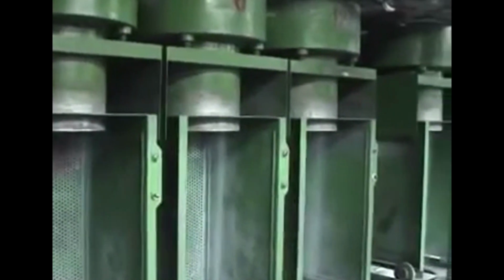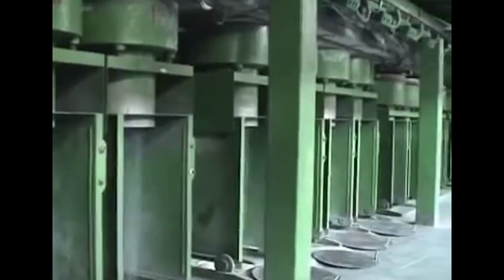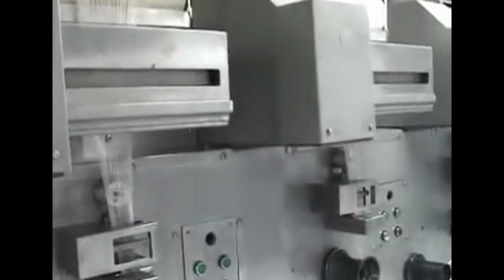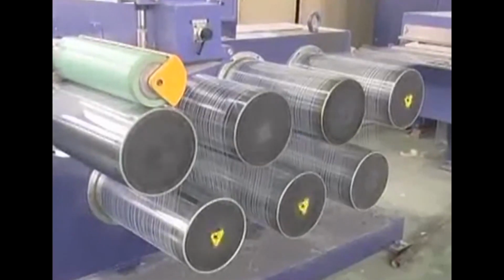So, from the holes of the spinneret, it comes out in thin form and becomes a filament. It gets solidified by hitting the air. When you check that particular filament, it will not contain alignment of the molecular chains. These molecular chains need to be aligned to the fiber axis in order to make it stronger.